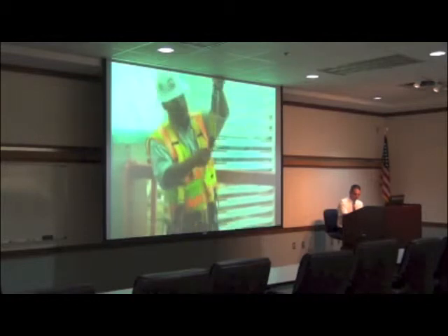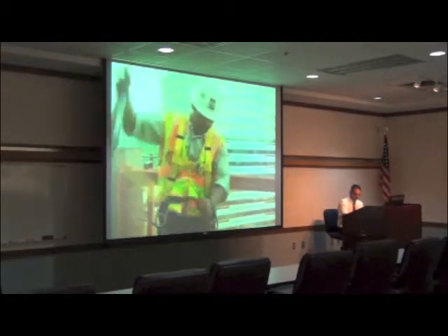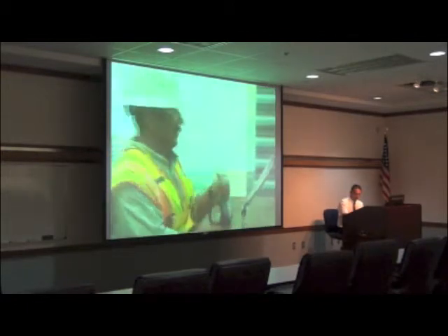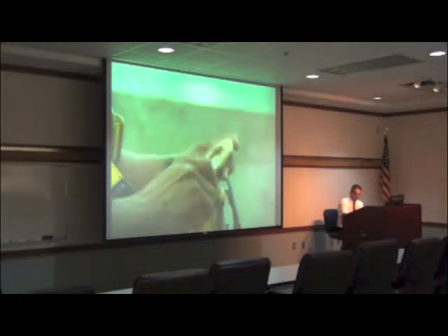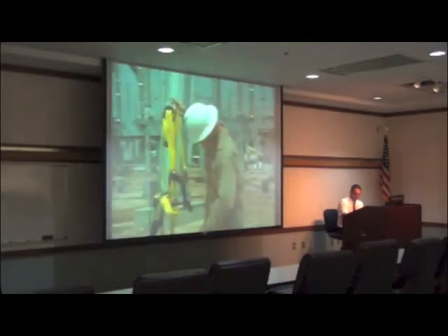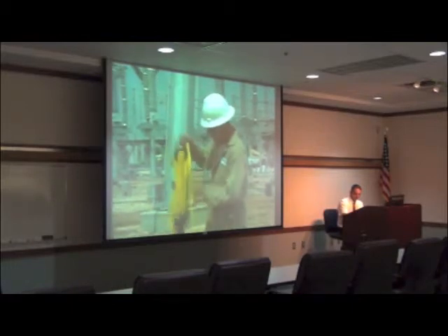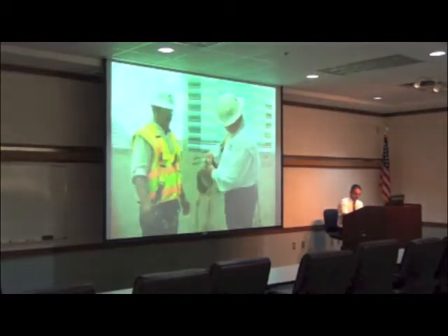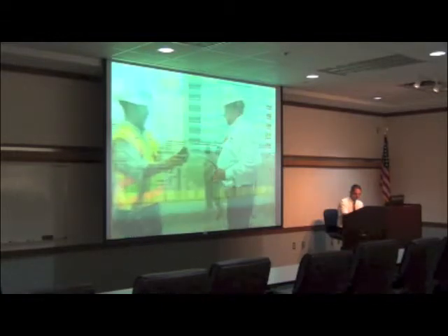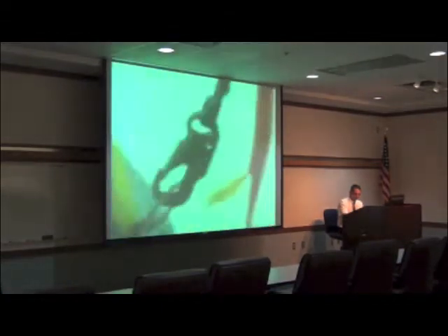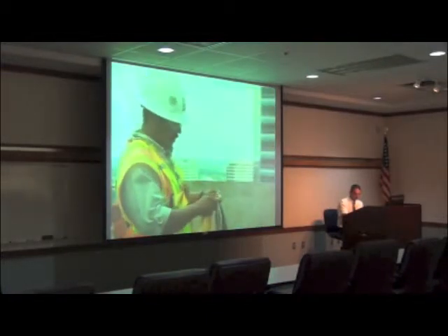Your employer will select personal fall arrest systems appropriate for the type of work being performed. Choosing the right component in each category is critical to safe functioning of the system and protection of the worker. Regulations state that personal fall arrest systems, including lifelines, must be designed, installed, and used under the supervision of a qualified person. All parts of the fall arrest systems shall be approved and compatible, properly maintained, and cleaned and stored when not in use.